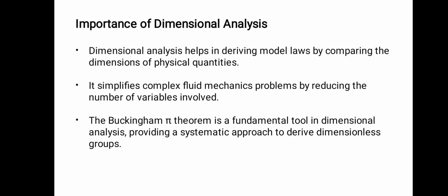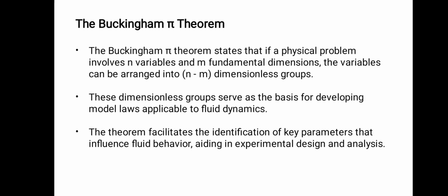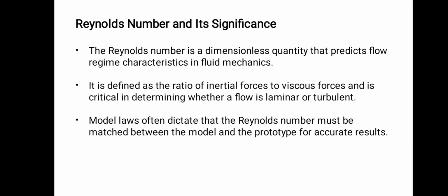Buckingham's pi theorem is a fundamental tool in dimensional analysis, providing a systematic approach to derive the dimensionless groups. Buckingham's pi theorem states that if the physical problem involves n variables and m fundamental dimensions, the variables can be arranged into n minus m dimensionless groups. These dimensionless groups serve as a basis for developing the model laws applicable to fluid dynamics. The theorem facilitates the identification of key parameters that influence the fluid behavior, aiding in experimental design and analysis.